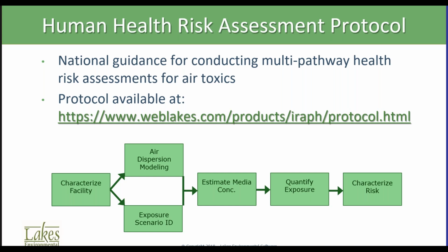In the past, it was also done with the ISCST3 model. Also characterizing the exposure scenarios, which means looking at the modeling domain around these sources and looking at where health risk may need to be quantified. From there, you estimate the media concentrations, you quantify the exposure, and then you characterize the risk. All as part of the protocol.